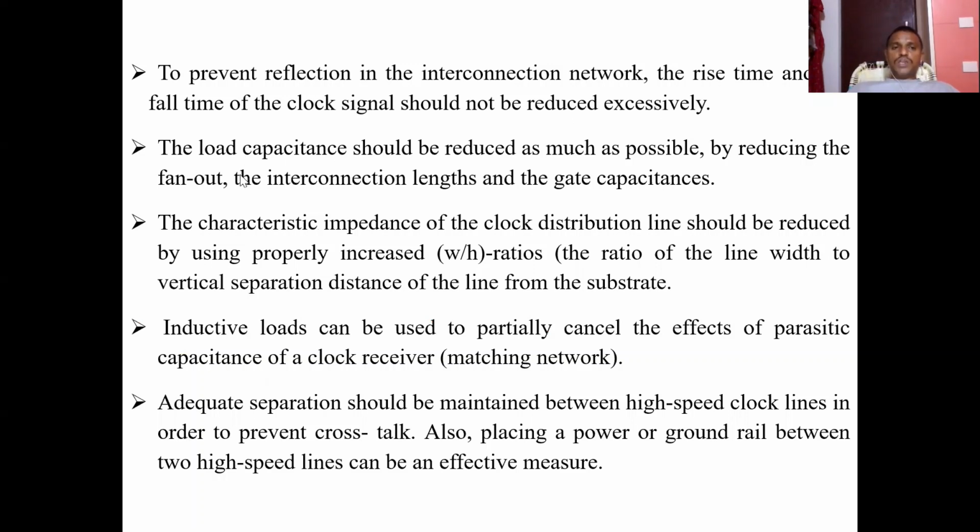The load capacitance should be reduced as much as possible by reducing the fan out, the interconnection lengths, and gate capacitances.